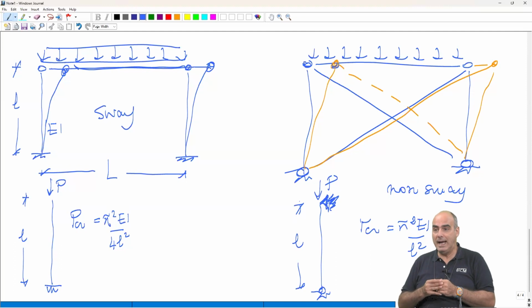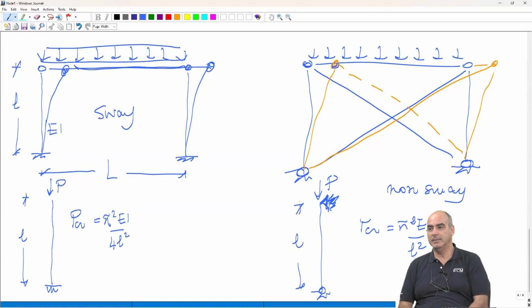It is what we design public spaces for, but also balconies and staircases. Balconies, because if you have a party, people go out. Staircases, when you have a fire or an earthquake and there is evacuation, people are all on the staircases. So you have more than doubled your loads.